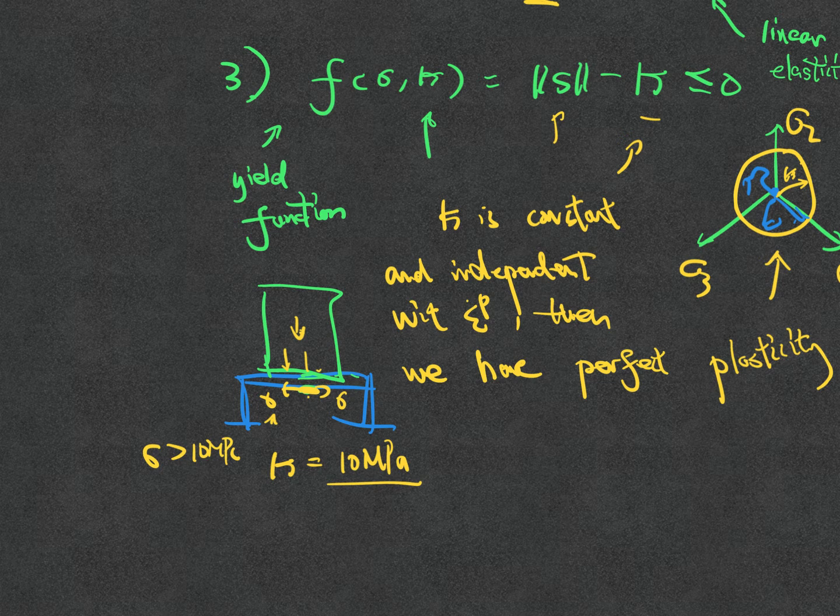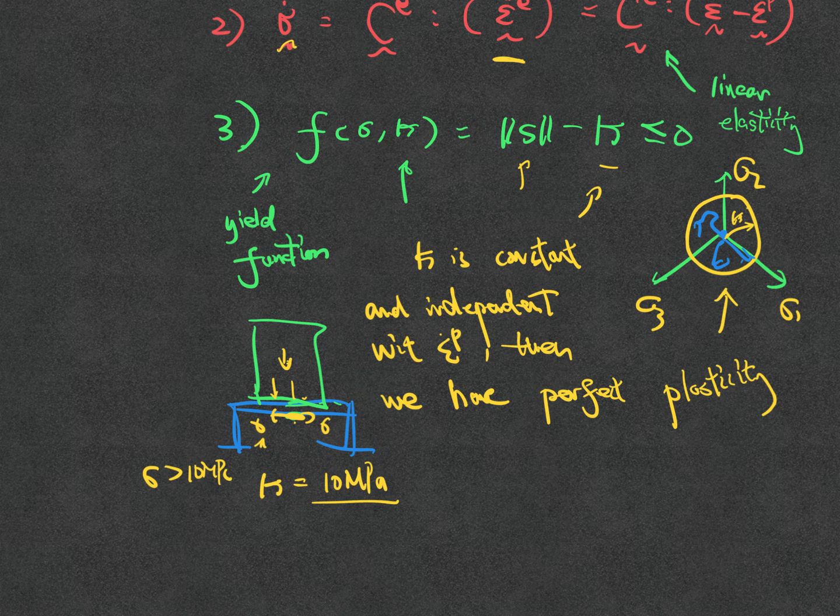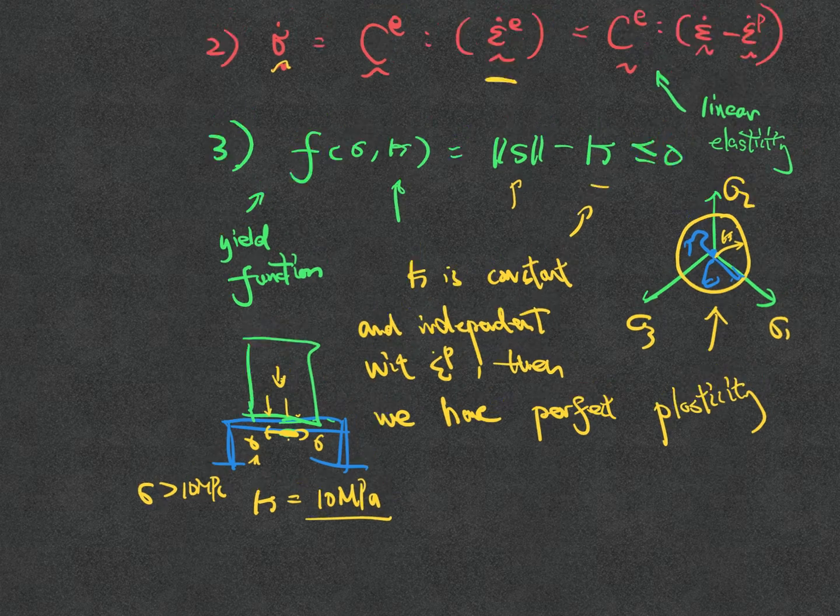On the other hand, if you solve a dynamic problem, you are able to update, but you will find that the table actually falls in the finite element simulation. Why? Because the difference between the internal force and the external force will be balanced by the inertial force. Then you start to generate accelerations of the material. If you have a quasi-static model, you will find those solutions. So unlike the elasticity problem, if you put a plasticity problem in finite element, there is a possibility that you would find the finite element solver has no solution, and that could be for physical reasons.